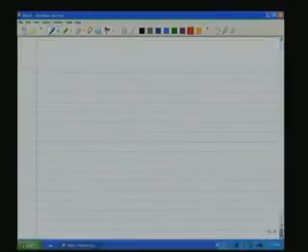You should know that the battery IV characteristics that we just saw are more of a general nature. The exact IV characteristic will differ from battery to battery, from type of battery to type of battery, from manufacturer to manufacturer, from ampere rating to ampere rating, and so on and so forth. So you should actually take the IV characteristic data from the manufacturer's data sheet for much more specific details.